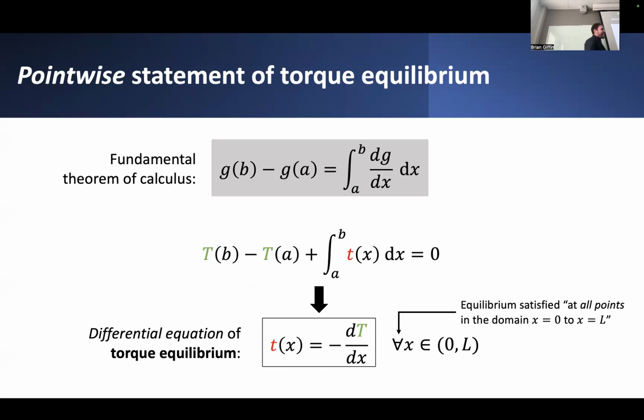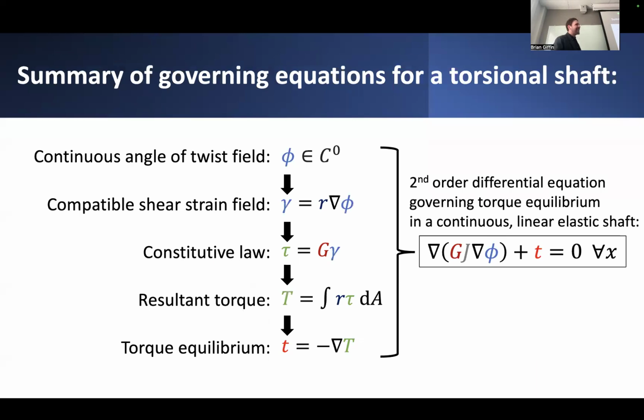And it turns out, as was the case in beams, as was the case in a lot of different scenarios, you can do a bunch of fun calculus and prove that, in fact, the derivative of this kind of torque, which varies along the length, is basically just equal to whatever this possibly varying distributed torque would be, the torque per unit length. So kind of fun. And again, you can put it all into one big equation, as I like to do, and solve for just the single field of interest, in this case, the angle of twist.